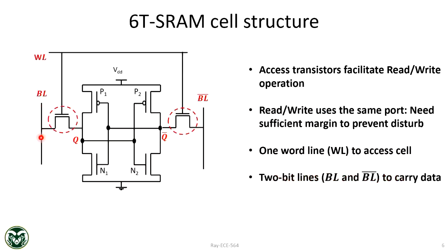So now you have charged this bit line. Now you turn this on. The cell capacitance, or effective capacitance at Q, will be 10 times smaller, much smaller. So even if the bit line loses a few picocoulomb, Q will be fully charged, because this bit line capacitor is much higher, right? That means it holds a lot of charge. A small amount of charge will go to Q, and that's how you flip the bit.